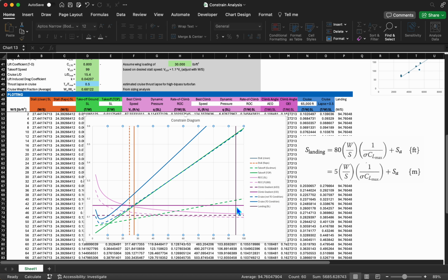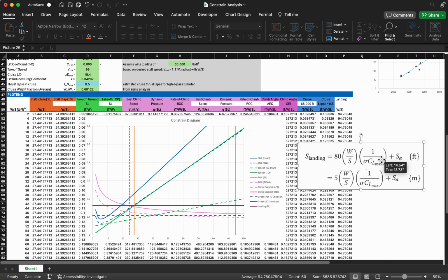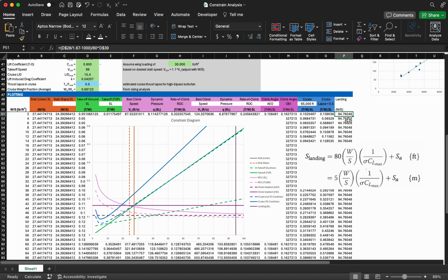Plot this, and we see this point appear way out in the distance. So now let's say we want to land at a high altitude airport and at high temperature maybe. So we're landing in Denver in the summer, 5,000 feet, and maybe it's 100 degrees out. So how do we account for that? Well, that can be accounted for through our density ratio.